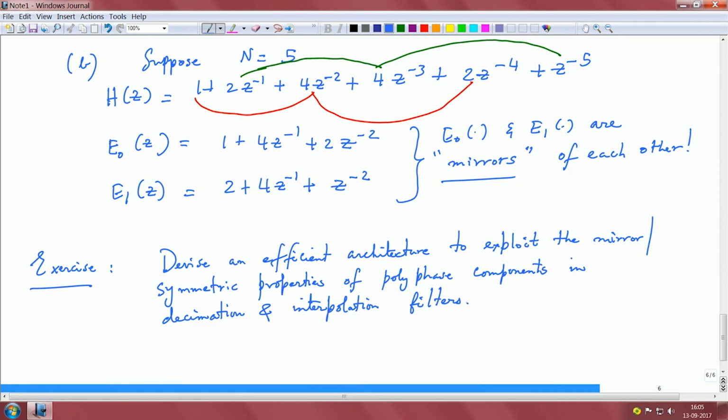Okay. So, we looked at decimation filters, we looked at interpolation filters, we saw how we can use polyphase decomposition and Noble identities for efficient realization. Of course that did not assume what the structure of the original filter has to be. But if we assume that we start with an FIR filter with symmetric impulse response, right, what can we say about the properties of the polyphase components?